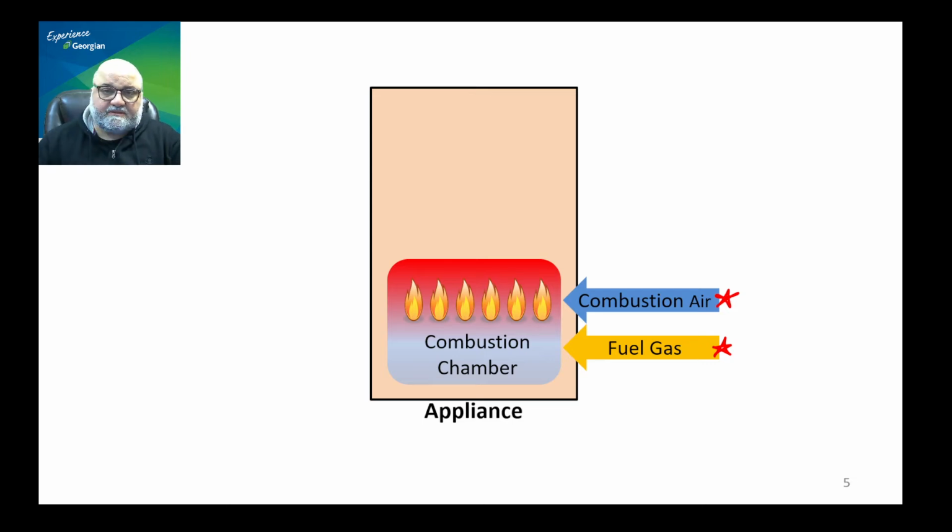In some places, you will need 100,000 BTUs. In some places, you will need 100 million BTUs. Depends on your application. The more BTUs per hour you need, the more volume of gas and combustion air are going to flow per hour into the combustion chamber.